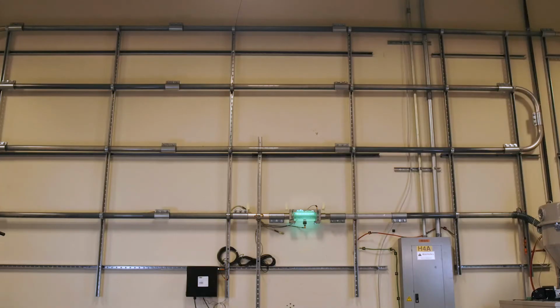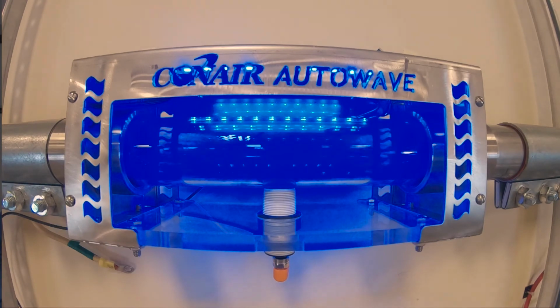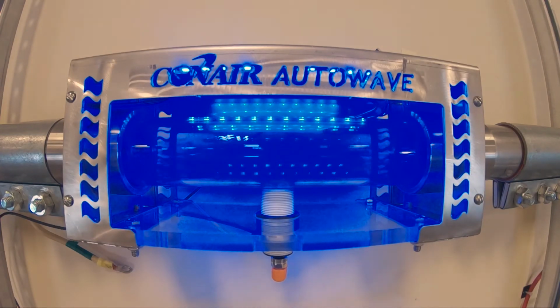of moving your resin. What I show on the screen is a quick cross-sectional image of what dilute phase conveying looks like, wave stream and then wave pulse. Wave stream is the optimal negative pressure pneumatic conveying system. I say that because you're able to get the maximum amount of throughput through that line at the lowest amount of conveying speed. Notice dilute phase conveying is very lean. It's a lot of air, a little bit of material. Wave stream has the optimal amount of pellets with respect to what throughput you're looking to achieve.